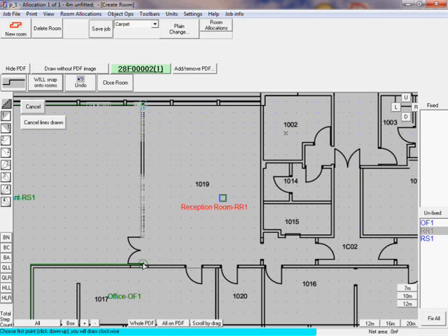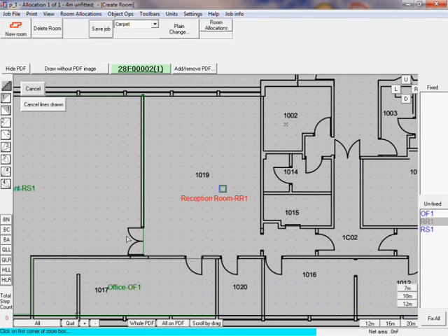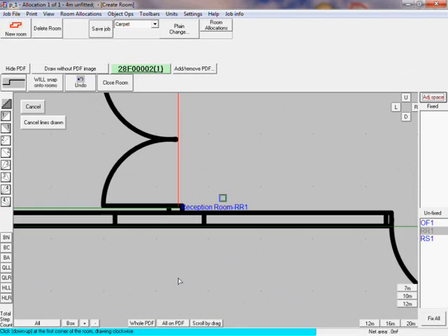Note, if we find that two different snap points are close together, then you can zoom in while you are drawing, using the box command. We do this like so. And now we can ensure that the snap to is not to this corner, but is onto this wall where we want it to be.